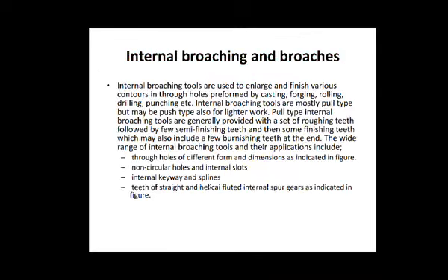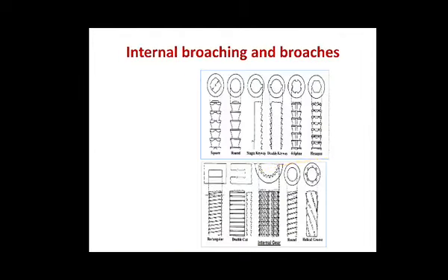So here, internal broaching tools and their applications, which include internal keyway, splines, non-circular holes, internal slots. Here you can see. Okay, so these broaches are used to get such shapes. This is what internal broaching is.